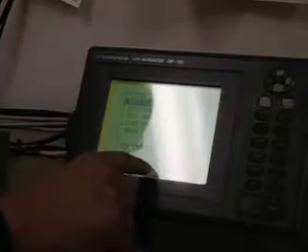So go to menu by pressing this. Under the main menu tree there are 9: display setup, track mark setup, erase track mark, alarm setting, manual calculation, number 7 GPS monitor, 8 self test, number 9 system setting. Most of the questions here are from system setting, number 9.